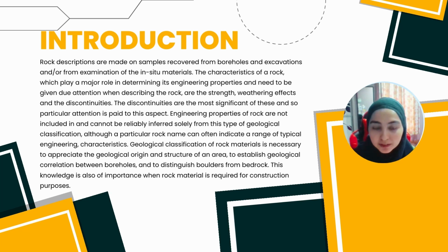Geological classification of a raw material is necessary to appreciate the geological origins and structure of a rock of an area, to establish geological correlation between boreholes and to distinguish boulders from bedrock. This knowledge is also of importance when rock material is required for construction purposes.